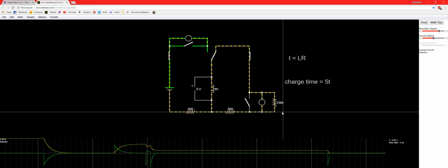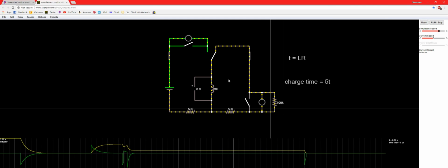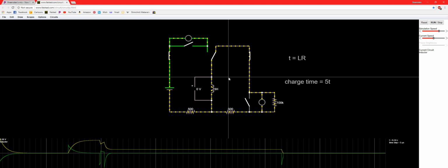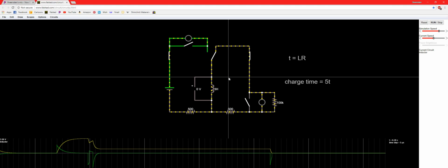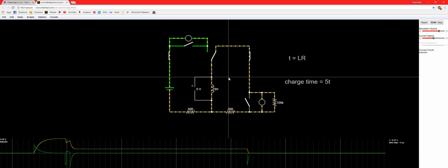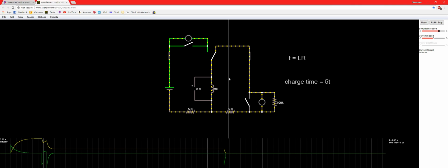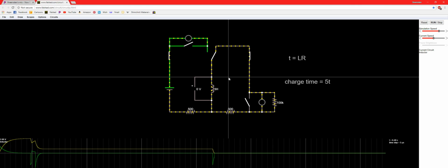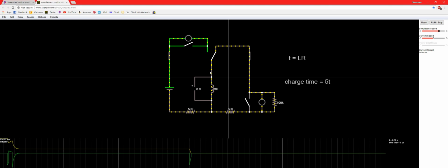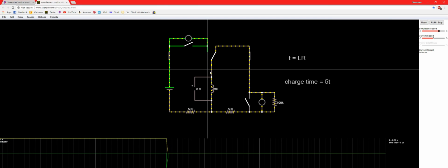The reason I have this resistor here is because inductors do have something called kickback, or recoil. What that means is if the inductor has no path to discharge the momentum, it's going to oscillate within itself, because it's constantly breaking down and building up a magnetic field that it can't get rid of that energy from, so it's going to oscillate until it has a way to discharge itself.